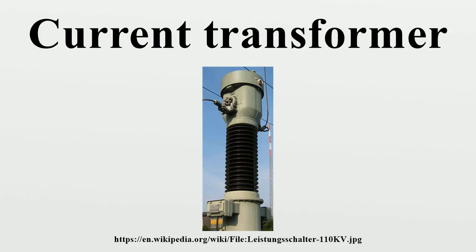Revenue-grade CTs drive the electrical utility's watt-hour meter on virtually every building with three-phase service and single-phase services greater than 200 amperes. High-voltage current transformers are mounted on porcelain or polymer insulators to isolate them from ground. Some CT configurations slip around the bushing of a high-voltage transformer or circuit breaker, which automatically centers the conductor inside the CT window. Current transformers can be mounted on the low-voltage or high-voltage leads of a power transformer.